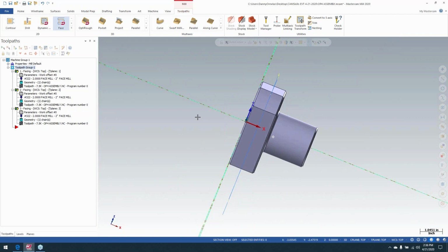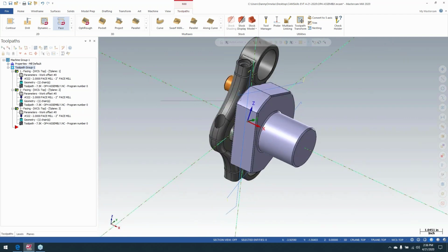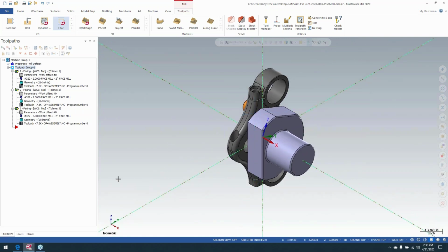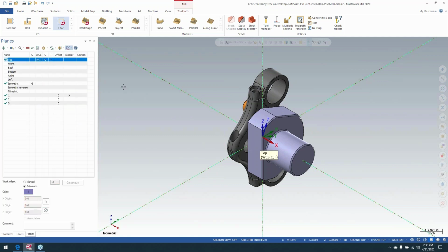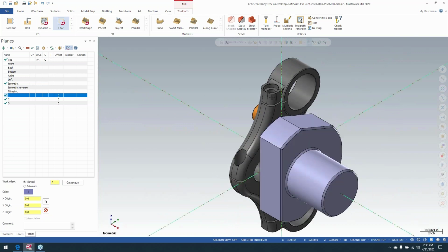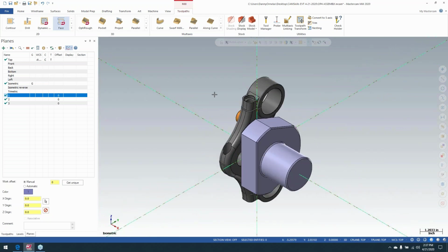So now I've machined the flats on the part. Now let's address the part here. This is another example of rotary where I may want to control the exact location of each of these features here. When I post it out and do a circle mill or a tap or whatever, the depth, I don't want to have to shift one work coordinate, because if I shift something here, it might affect something on the bottom side. So each one of these, I want to have its own little work coordinate system, so I can do the adjusting at the machine.